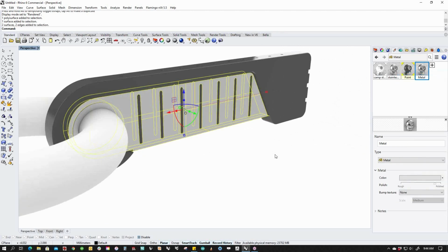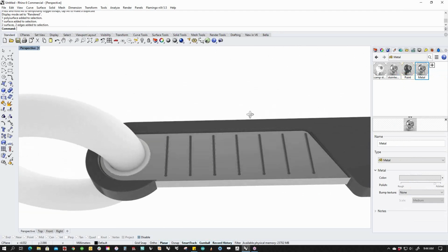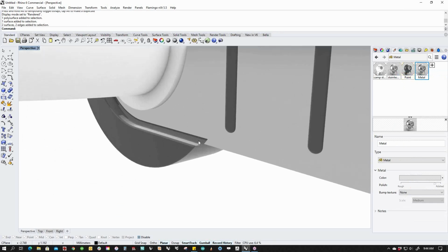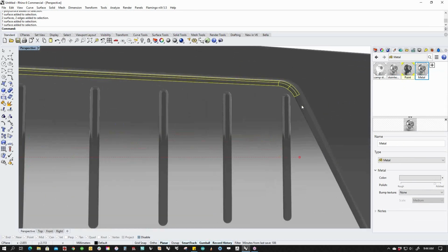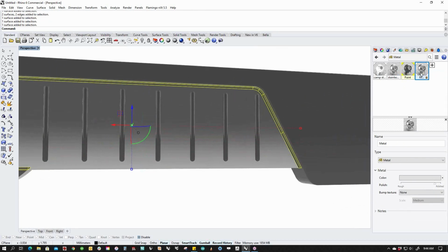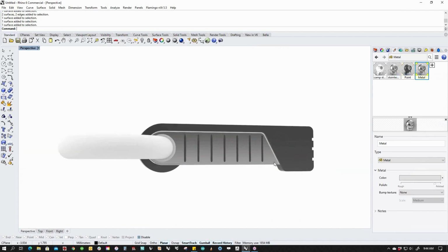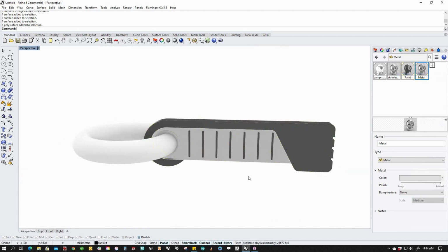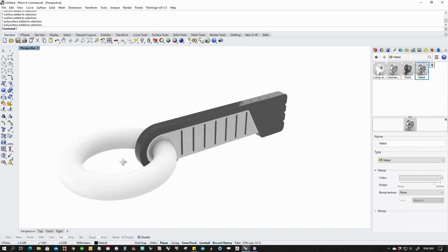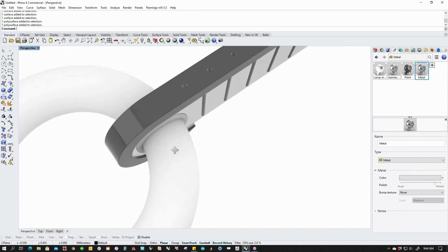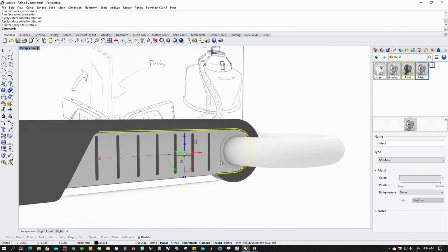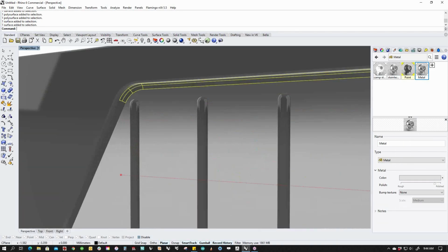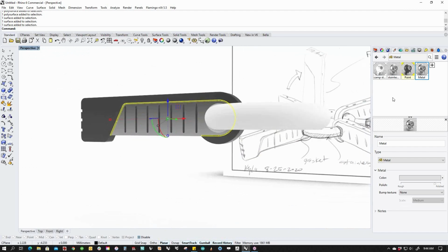Right click, and we're going to do a sub-object assignment. And what that allowed us to do is to pick pieces of a completed polysurface and add them to our selection and change the material. However, the cool thing about this is it's still a polysurface. It's still closed. It's still something that you can print or data transfer, anything like that. So that's new in 6, this ability to do sub-object selection.